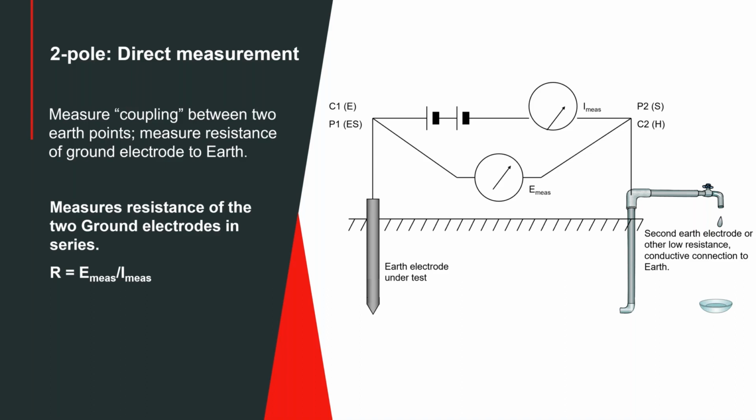In this configuration, the water pipe system, or something like a metal fence system, can also be used. The idea is that's an electrical connection, and this procedure is typically referred to as dead earth. What they mean by that is the return is not part of any electrical system.